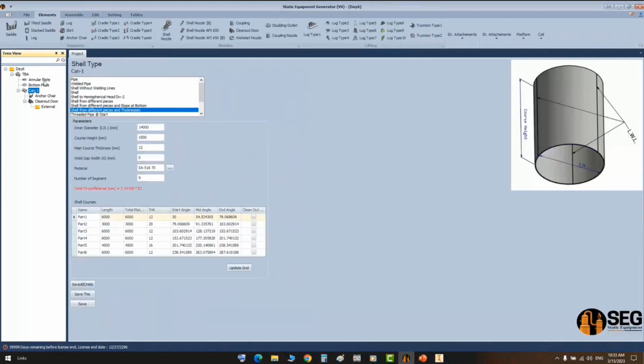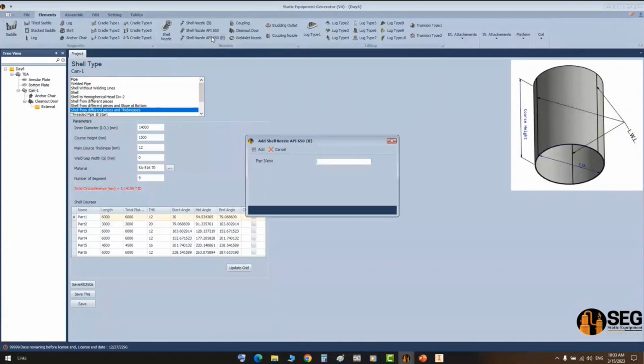So from here, let's select this can, and from that one, let's select. You can figure that you have nozzles according to ASME and the nozzles according to the API. So let's select nozzle according to API with external and internal projection. So you have this type and that type. Type B, which is nozzle with internal and external projection. So let's add N1.